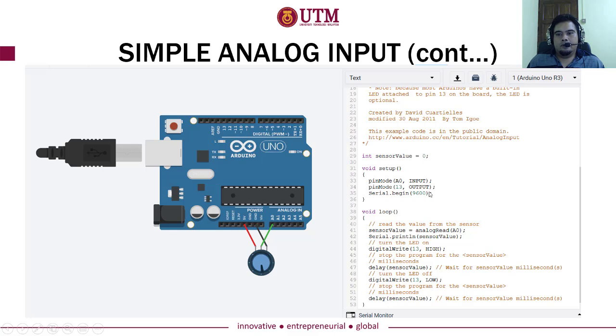Okay, the first time you saw this was when I showed you the hello world example, when we wanted to use printf, which is equivalent to Serial.println here. It will display anything when you execute this. It will display to the serial monitor, which is the Arduino borrowing your computer screen to become the monitor display for Arduino.